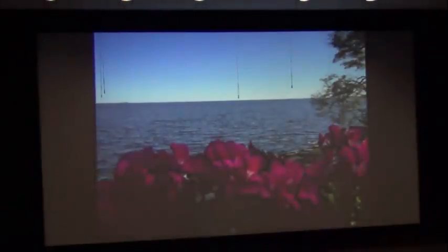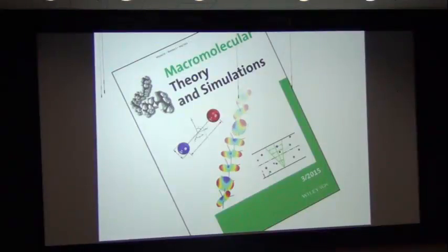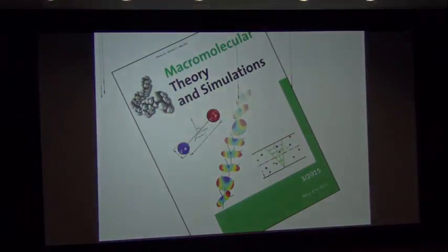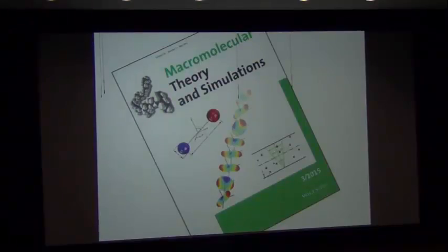Another picture of the lake, and I'm getting closer to the end of the lecture here, but I really had a fascinating summer. I had a student come and visit this summer. She read our papers, and she noticed that when we wrote this paper just about the orientation, by the way, let me tell you about this paper. I told you that some parts of the orientation distribution are contributing to the shear stress. Some parts are contributing to the normal stresses. Some parts to both. Some parts to nothing at all that we can measure with a rheometer.